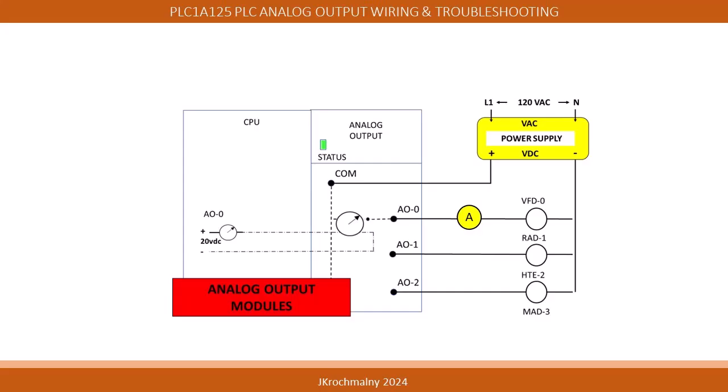Shown in this graphic is the placement of a milliamp configured multimeter between the A0-0 PLC output terminal and the analog load. The amperage configured multimeter scaled to read in milliamps can then measure, in this case, between 4 to 20 milliamps. It is important to understand that when performing milliamp measurements on DC electronic equipment, the meter is placed in series between the source of the current and the receiving device. Also, it is important to observe circuit polarity.